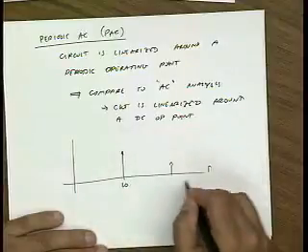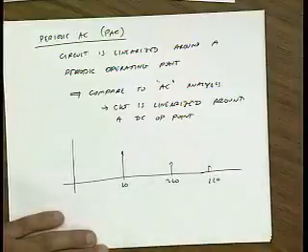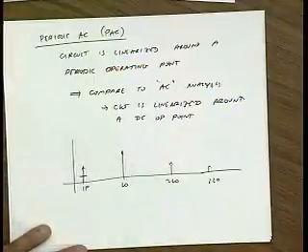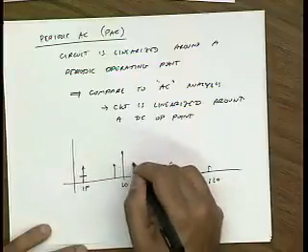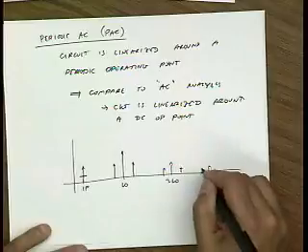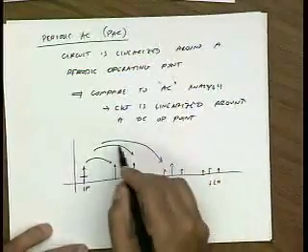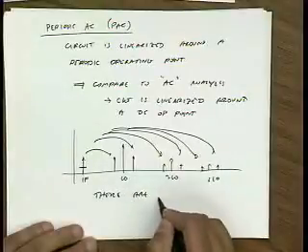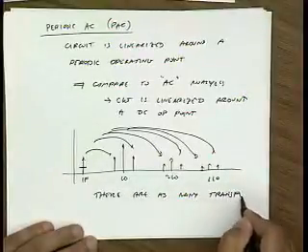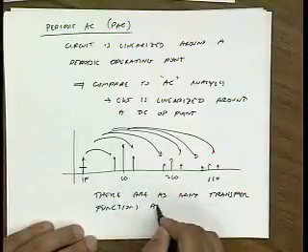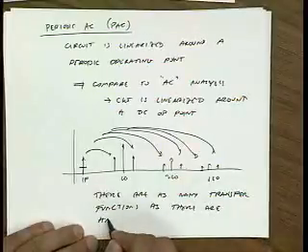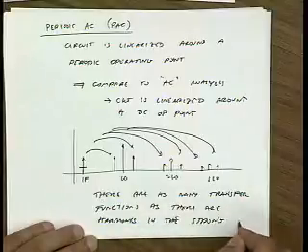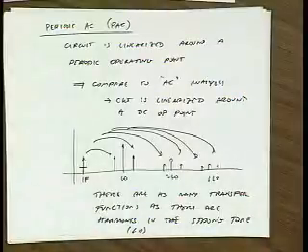Here's my LO, here's my 2LO, my 3LO. And for instance, let's say I apply a signal at IF, and it's an upconversion mixer. Well, I know that this can mix to these sidebands, it can mix to these sidebands, it can mix to these sidebands. So which transfer function should we look at? And how many transfer functions are there? There are as many transfer functions as there are harmonics in the strong tone. Right? And that might be the LO in the case of a mixer.